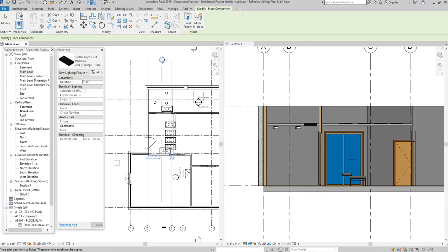But the problem you're going to run into with that is that you're creating a floor with gypsum board on the bottom. You're not creating an actual ceiling. And so the problem you may run into is that your lights won't host into that floor, right? Some will, if you can find generic ones, but others, like these predefined Revit ones, a lot of them won't. Okay, so it's tempting to say, well, to keep things simple, I'm just going to add gypsum board to the bottom of my floor.